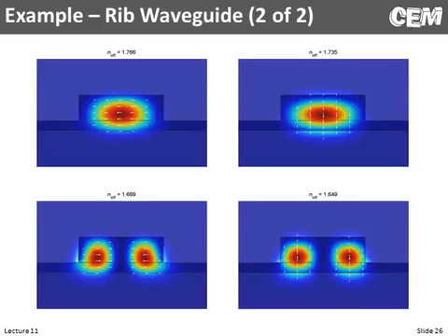So we throw that waveguide into our model, and here are the modes that come out of the rib waveguide. And these are fully rigorous models. What we can see is that we have a fundamental mode. And so here's our fundamental mode. It has the highest effective refractive index. Our next order mode looks very much the same, but notice how this is polarized almost completely linearly left and right. Now this is almost completely linearly polarized up and down.